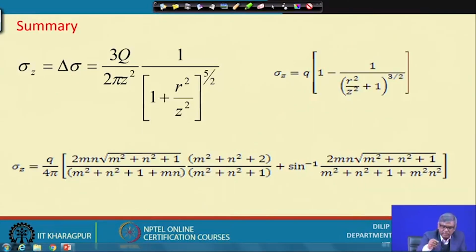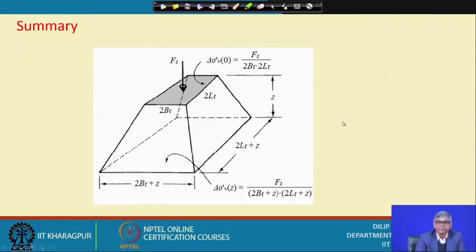but in soil mechanics, unless it is specified, we can generally use a quick method, that is trapezoidal distribution method. Generally we consider the two vertical, one horizontal. That means, if you go down this much, then horizontally it will be half of that.